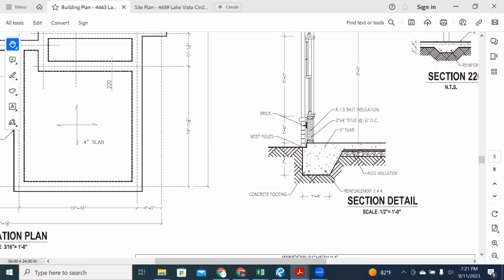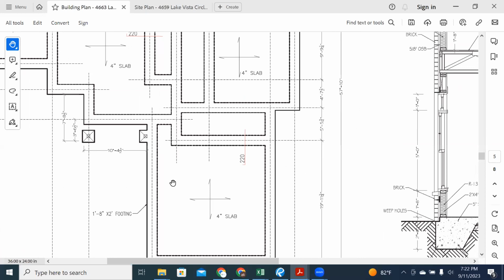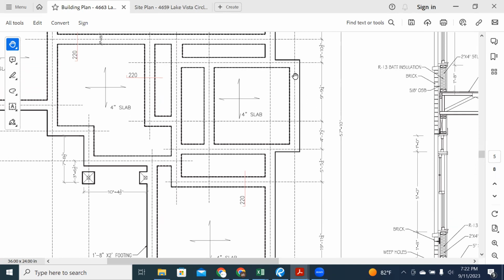So long as you have the width, 1 foot 8 inches, the depth, 2 feet, and the 2 iron rebars, number 4, because they do have different numbers for different weights, as long as you have that, they'll go all the way around it. And in the video, I actually jumped in the footing and was walking around as I took that video.